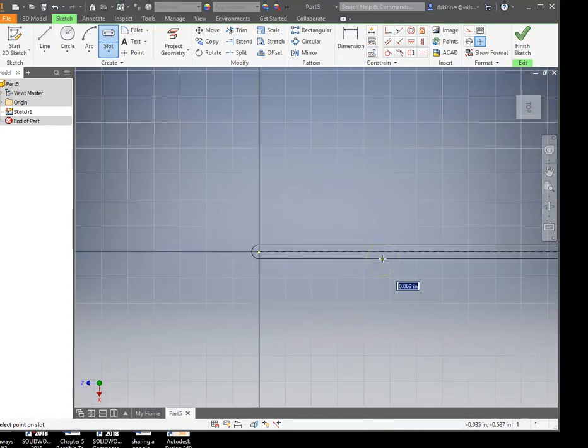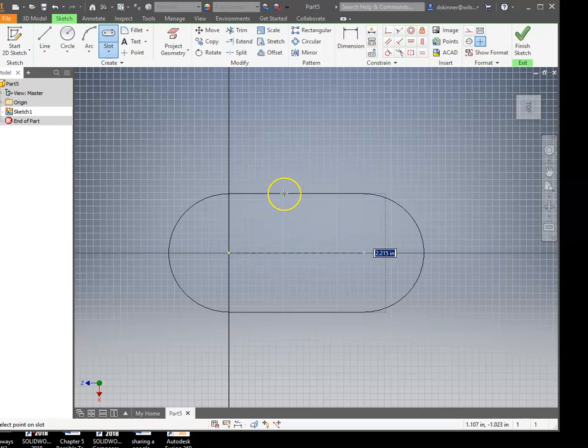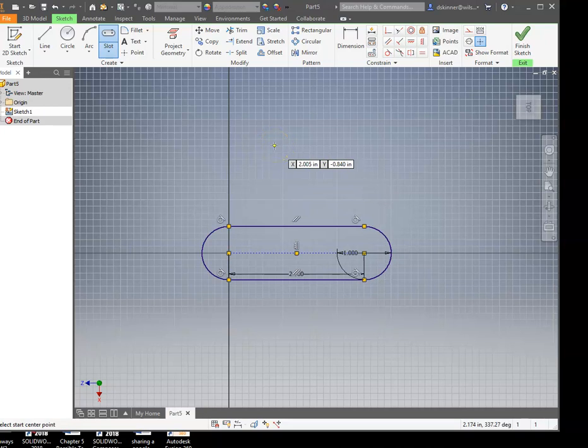And then outward, oh, there you go. Then outward it goes a diameter of 1. So that's my slot. Now I also want a thickness for that in this view. For this one, I could extrude that shape and then use another shape, but often you can incorporate a couple of items in one sketch. Just like you could draw an object and draw a hole in it, or extrude a donut, I'm going to do something similar with the slot.